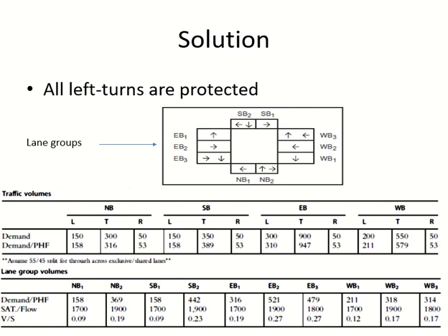Once you have converted it to flow rate in passenger cars per hour, you have to assign the flow rate for each lane group. For example, if a lane has two movements, you will add the flow rates of these two movements. If a movement spans more than one lane, you have to divide the movement into those lanes, and so on. We did this. After that, you need the saturation flow rate. You will divide the demand flow rate for each lane group by its saturation flow rate, and this is what we got in the end.